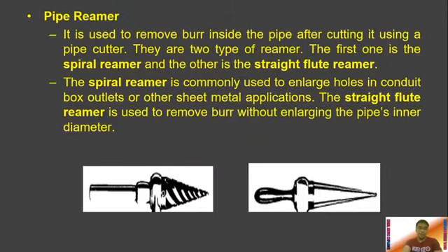Then we have the pipe reamer. If we are going to ream the pipes, usually we will use a file so that the wire will not be stripped, just like what I said a while ago. But we could also use the pipe reamer, which is much more comfortable to use. It is used to remove burrs inside the pipe after cutting it using a pipe cutter.